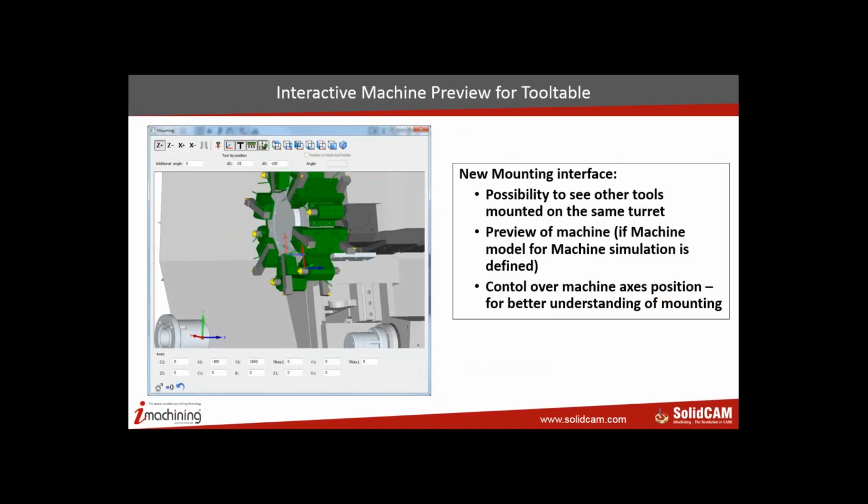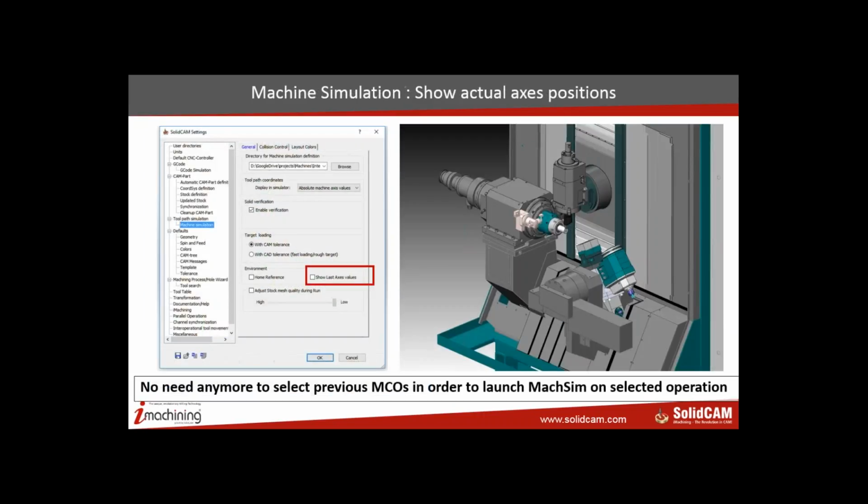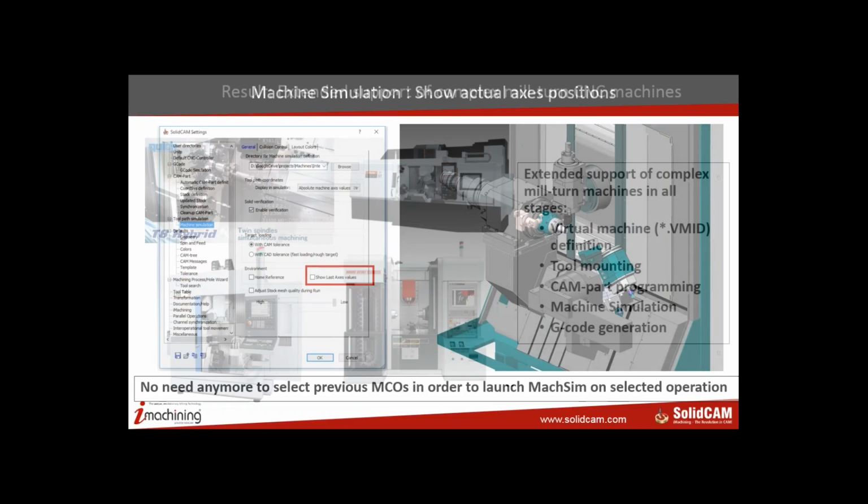Interactive machine preview of the tool table, which I'll show you shortly. You can now see the tools as they would be presented on the machine, in the holders, on the turret, in relation to other tools, in relation to the turret, in relation to everything else on the machine. It's as if you were looking at it on your screen through the window of the machine, so it's a lot easier to see where things may cause problems. You can show each axis in the position where they are, so no need to select a previous machine operation to show where you currently are. You can just see straight away where you're going to be.